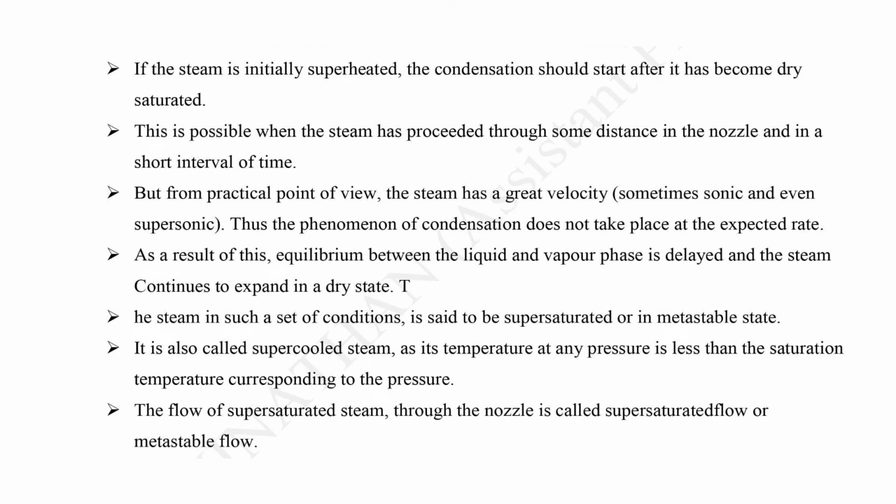If the steam is initially superheated, the condensation should start after it has become dry saturated. This is possible when the steam has proceeded through some distance in the nozzle and in a short interval of time. But from a practical point of view, the steam has a great velocity, sometimes supersonic. Thus the phenomenon of condensation doesn't take place at the expected rate.